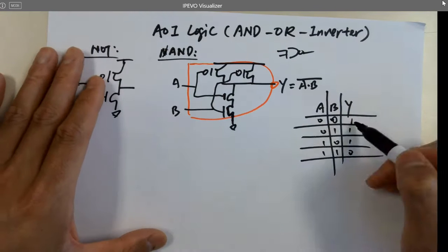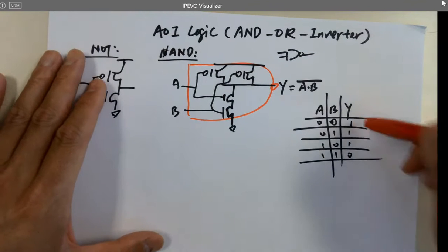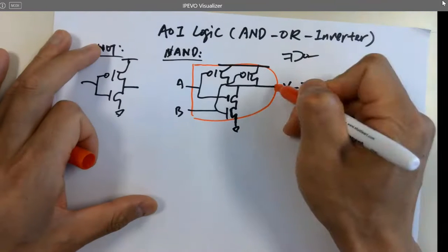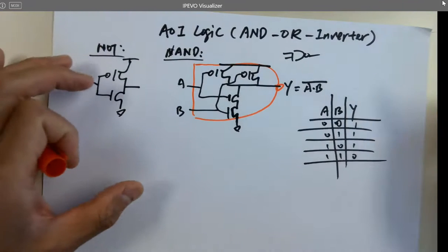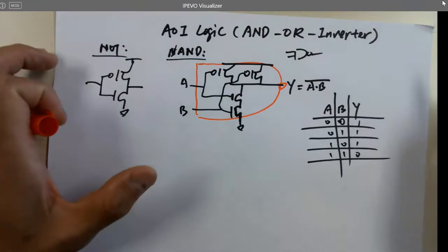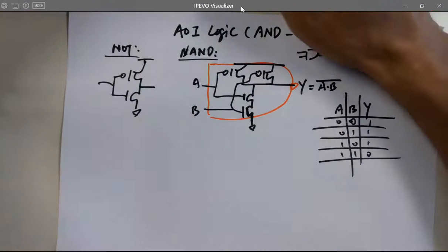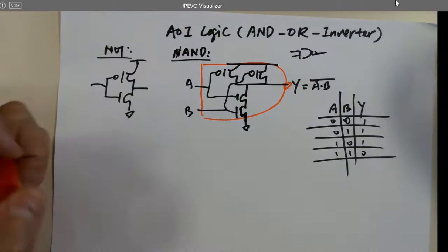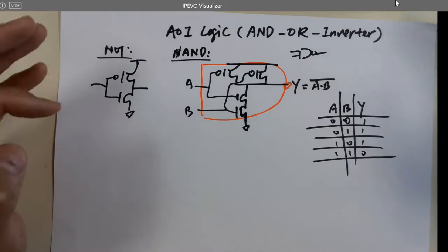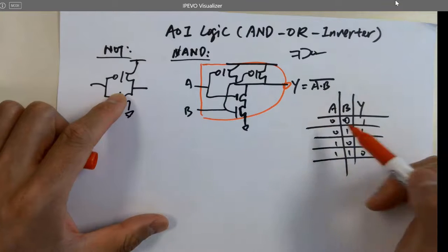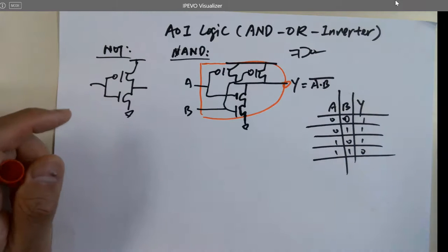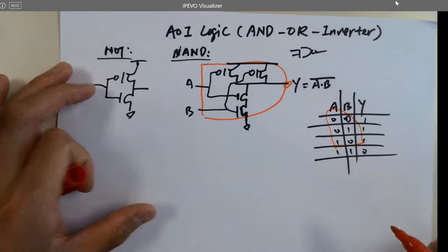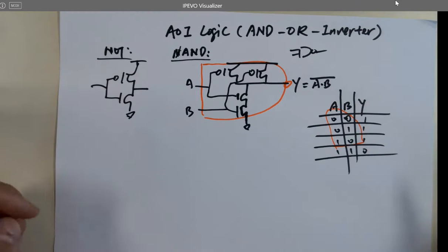For these results, the output is 1, which means you want the output pin here being pulled up to VDD. It's not mysterious, right? This is the truth table of the NAND logic, so what we are doing is just designing the circuit to implement it. Whenever we have these inputs, we need a 1. That's it. Whatever can implement that logic is good. It's a NAND gate.